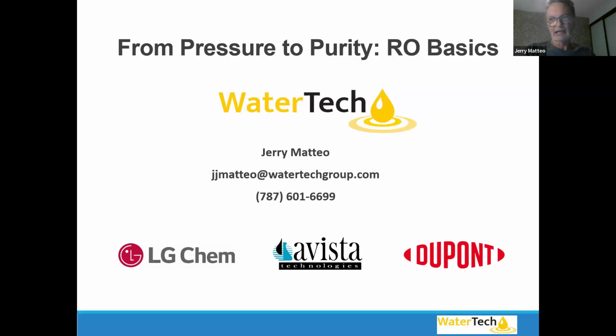And we don't want that iron particle going to our membrane. Okay, I should qualify that. It also depends on what level. Our chemical software for RO will show us, using the Langelier saturation index, if you give me your water analysis and we see what the amount of iron and manganese are in there, a very clear graphic that'll show us at various recoveries, depending on how much water I'm trying to make with my RO, where I will start to scale and precipitate that iron in my membranes. And then we can pick anti-scalants and try to keep it in solution.